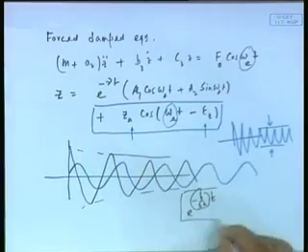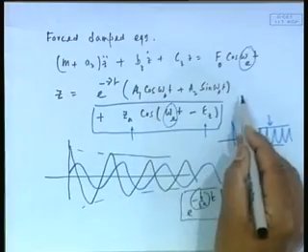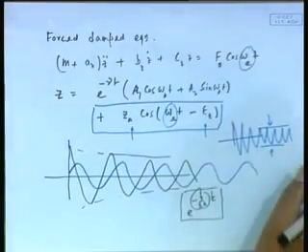Remember, it is nothing to do with the structure, it is connected to the decay part, and we are only looking at the steady part of the solution. Even for an offshore structure, when the wave comes I am looking at a 1 hour, 2 or 3 hour kind of solution, not 10 seconds that goes off. And the second thing is that waves are always existing, you cannot fix the time when it started. Suppose you go on board today, it has been oscillating since yesterday, it is not that it started from a calm sea suddenly. So, what you see is always a steady solution, the decay part is just not there, and simulation also shows this. In fact, we will see later by numbers how fast b by 2a decays.